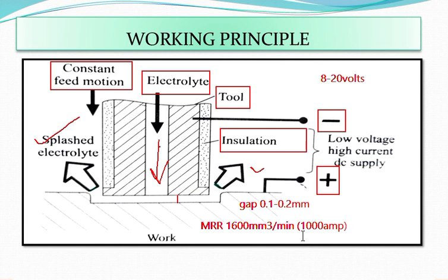Though it appears that since machining is done electrochemically, the tool experiences no force, the fact is that the tool and the work are subjected to very large forces exerted by the high pressure fluid in the gap.